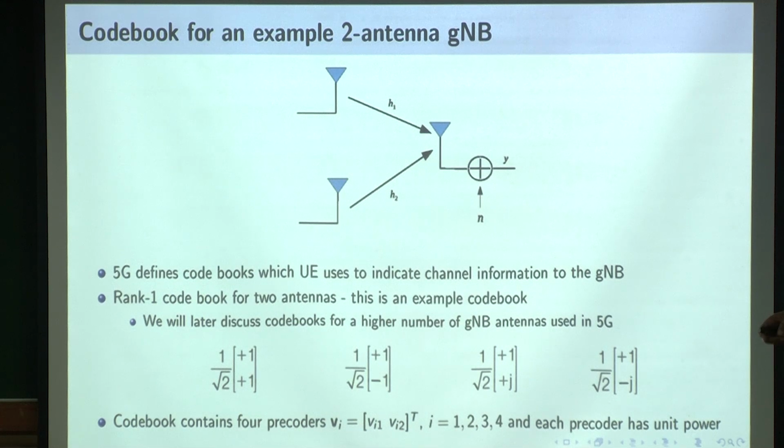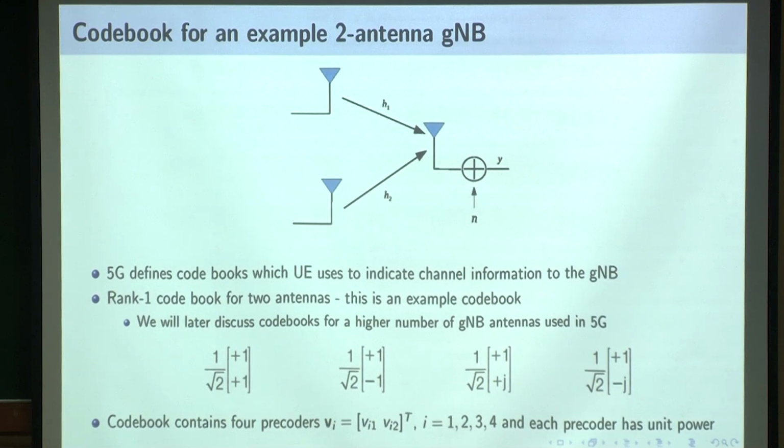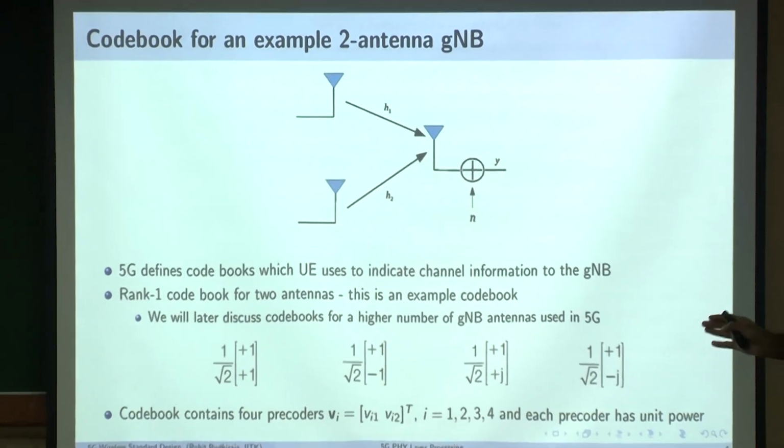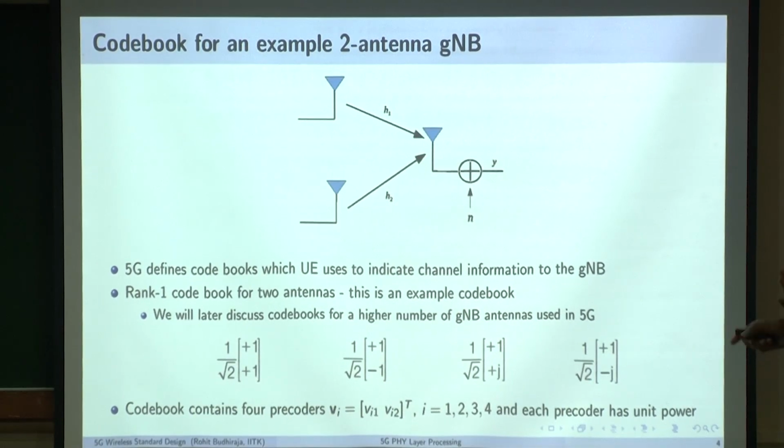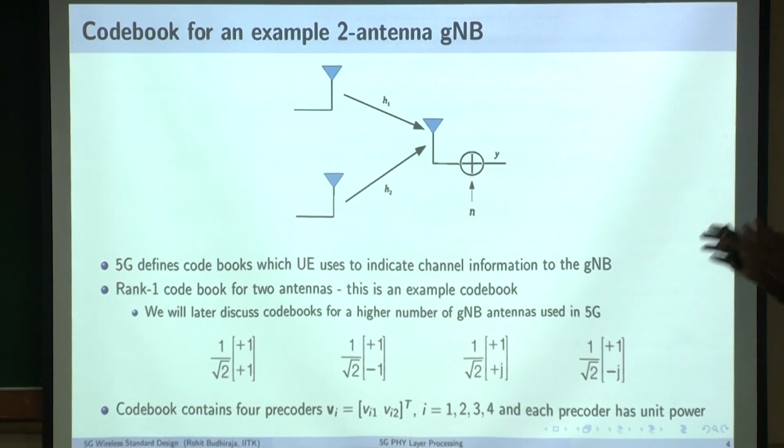So the kind of simulations people do is, you design a codebook with 4 different angles, you design a codebook with 64 different angles, and see how much performance degrades in this 2-bit quantization when compared with 6-bit quantization. People realize that this gives you close to the best performance. After that you get diminishing returns by increasing the number of quantization levels. So for this kind of system, this kind of codebook is enough. That is how it is implemented for a 2 antenna system.